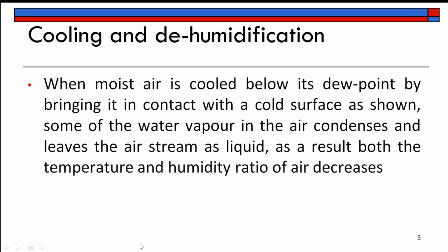Cooling and dehumidification. This is the process of reducing the temperature, cooling, and dehumidification, removing the excess moisture content from the air. When the moisture is cooled below its dew point, you know what is dew point temperature. If you have any doubt, please refer to the previous class. When the moisture is cooled below its dew point by bringing it in contact with a cold surface, I will show you the diagram, some of the water vapor in the air condenses. So condensation happens. During condensation, obviously, a cooling effect will be produced. So water vapor will condense, and dehumidification, removal of moisture content from the air, also happens.